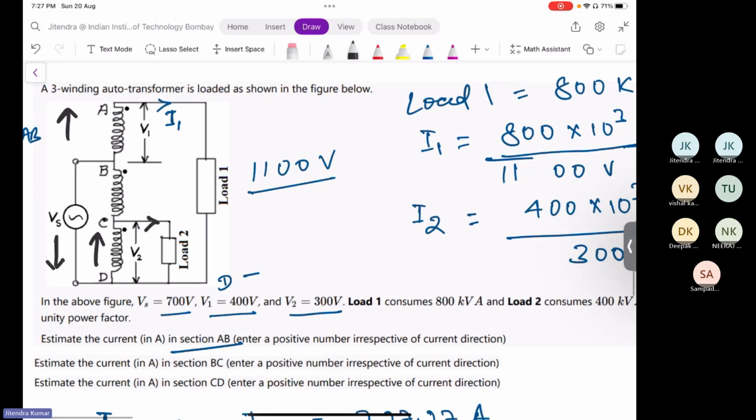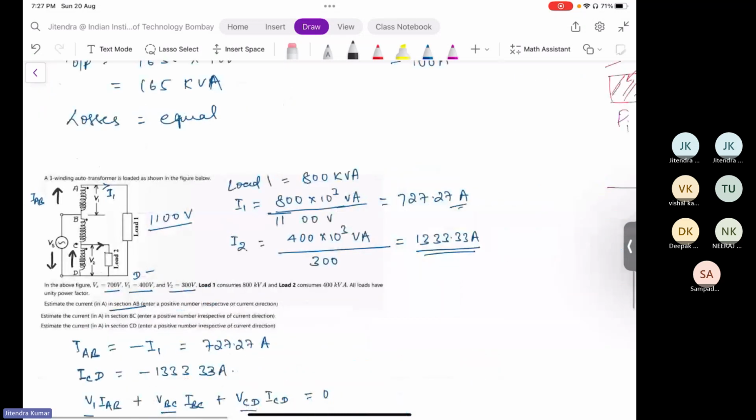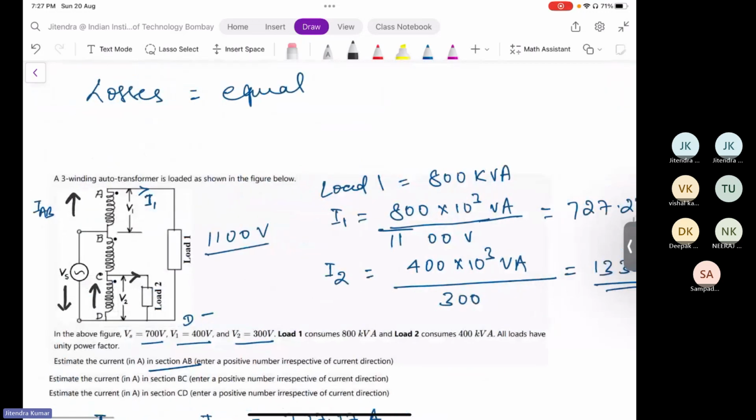So, at the end, if we have computed BC as positive, right? If BC is computed as positive, it means very less kVA is required from BC to cater load 1 than load 2. And it also implies that CD winding is not solely responsible for load 2, because BC is also catering load 2 in a huge way.